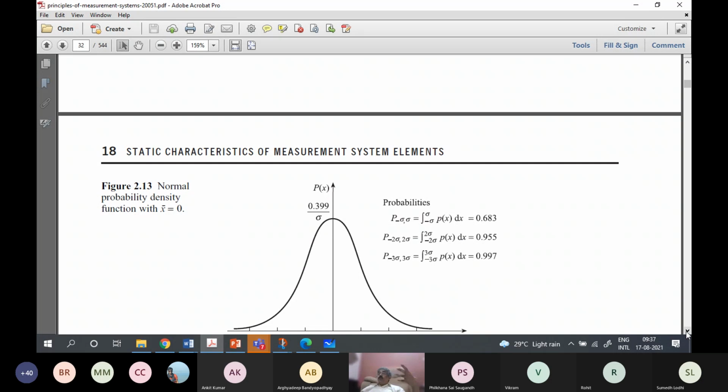So when you have a sensor which has a nonlinearity specification, a repeatability specification, and a resolution specification, you have to understand what kind of errors you will get in a given circumstance due to the effects of all these things, right? These are all small deviation specifications, but they are due to different reasons. Nonlinearity is due to you having simplified the actual model for ease of use. Something is really nonlinear, you are calling it linear, and then saying that it deviates from linearity.